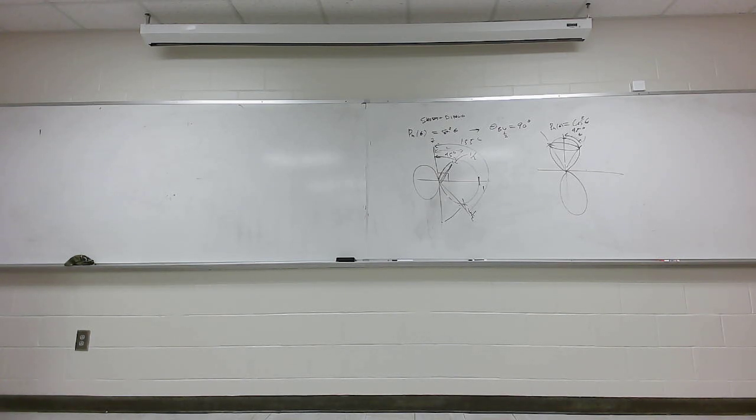So it goes out to Ball Aerospace for testing. And when they tested the antenna, the guy calls me up and he says, you know, that antenna's got a standing wave ratio of 4 to 1 on it. All right? A standing wave ratio of 1 is acceptable. 1.1, okay. 1.2, okay. Anything over 1.3, 1.4, somebody messed up. When it's 4, it's like a moron design. You can't get any worse.